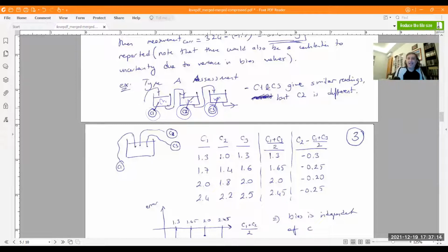Note that during the experiment, these 3 tanks are going to show different concentrations, so it is realistic to obtain different values from the conductometers. But for some reason, we felt suspicious. So in the same concentrated container, one by one, we measured the concentration using each of these conductometers. And we realized that conductometer 1 and 3 gave almost identical results, whereas conductometer 2 gave different results.